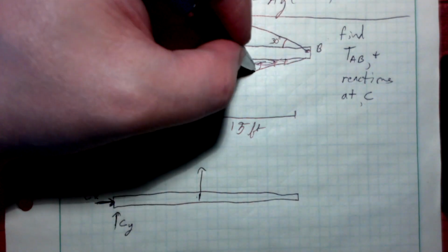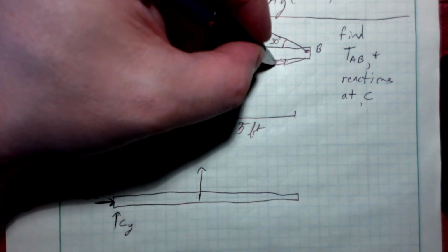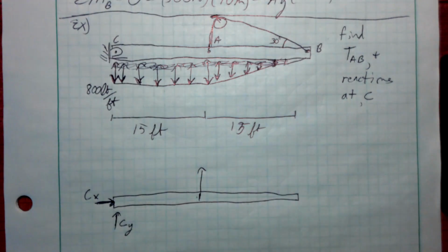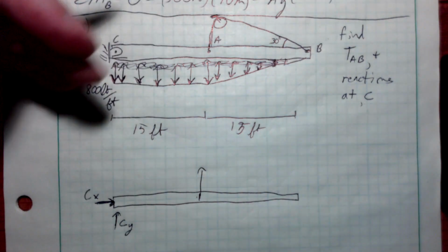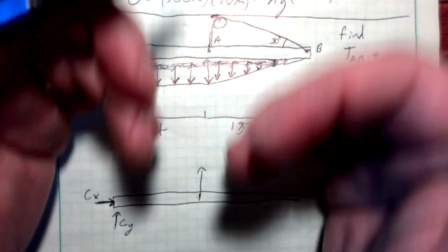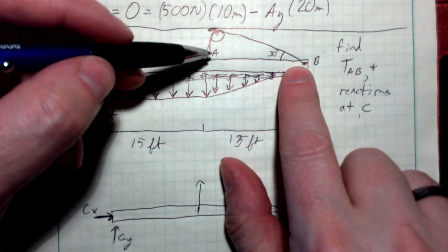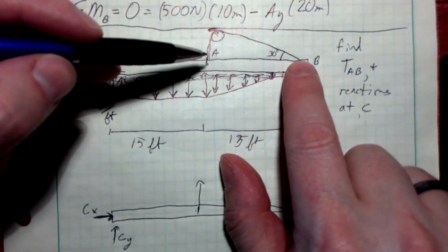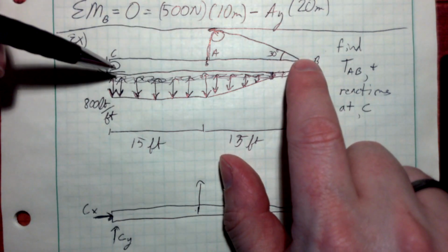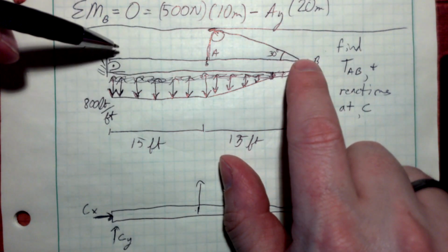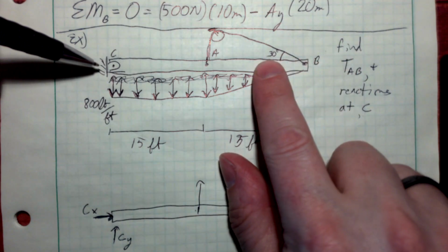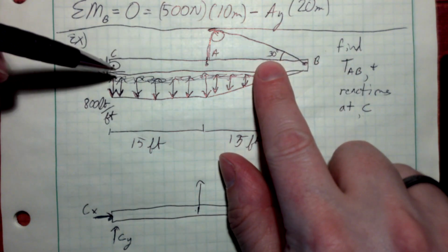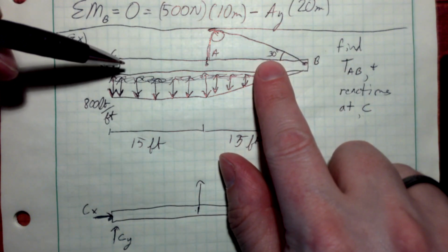Yeah, if we push this beam up with this distributed force, then it's just going to push up, right? There's nothing pushing it back down except for a little y direction force here. But if we pull it down, these cables up here are going to basically hold it in place. So I've got cables holding it up. I've got y direction force here also helping hold it up, and then part of this tension is in the x direction, so it's going to get counteracted by this x direction force to keep this thing in place.